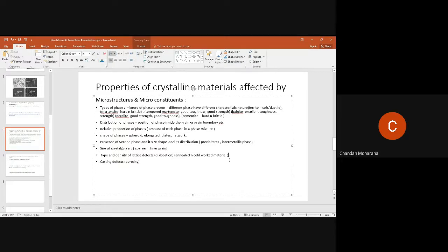Similarly, many dislocations will generate in the material. When a lot of dislocations are there, they will start interacting with one another. They will get tangled up, and the dislocation movement will be restricted. What is that phenomenon called? When the dislocation movement is restricted, it becomes sessile. Dislocation pile-up is a different thing. Pile-up means they move towards the grain boundary and are stopped by the grain boundaries. No, that is the strain hardening phenomenon.